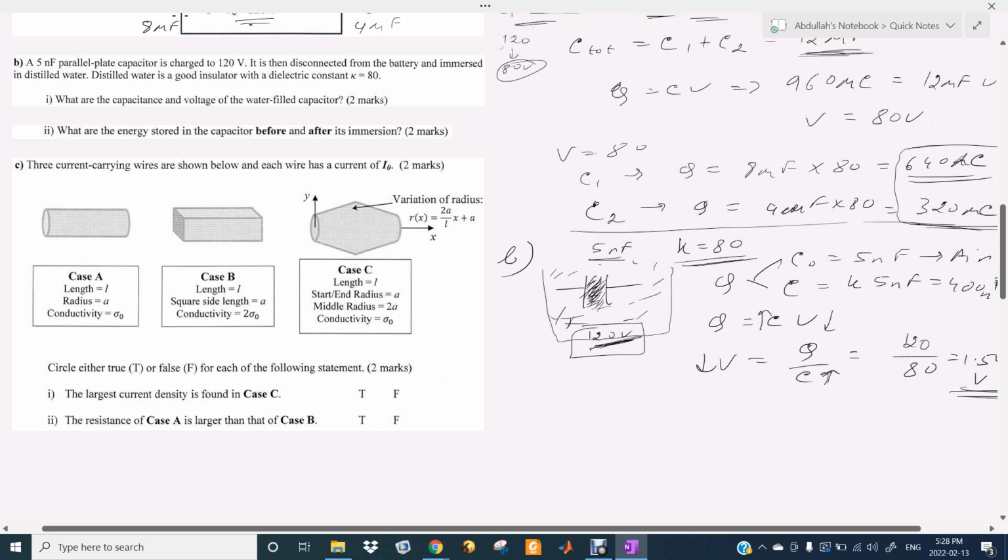Now remember, if there is a short circuit, or if it's connected by a wire, that's the same potential on the same node. Let's say you have a capacitor, with one terminal as node A and the other terminal as node B. For this capacitor to be parallel with another capacitor, let's say this is C1, you need both the nodes to be connected directly, right? So if I connect this by a wire,